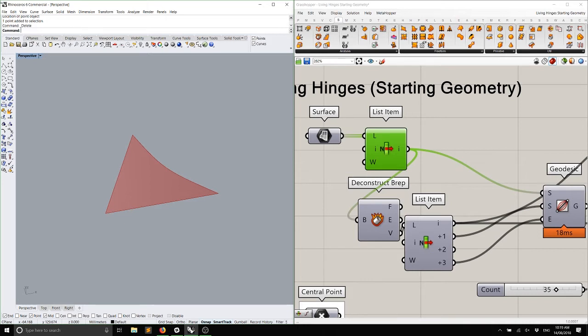They now make that little capsule like so, with a little hinge that allows the capsule to open and close but keeps the two pieces together, and it's actually made of the same plastic, okay? And so what they're doing is relying on the flexibility of the plastic to actually hinge the element. That's a living hinge. So it's a hinge where the material itself allows for that rotation, yeah?